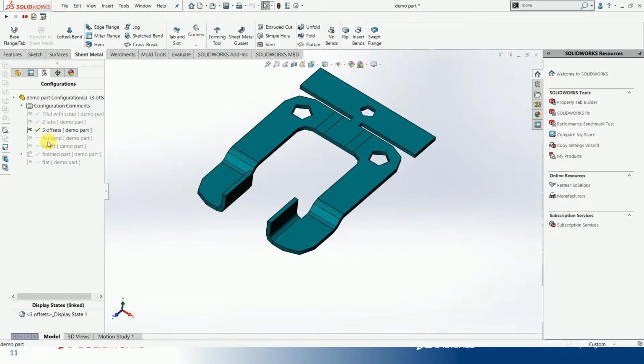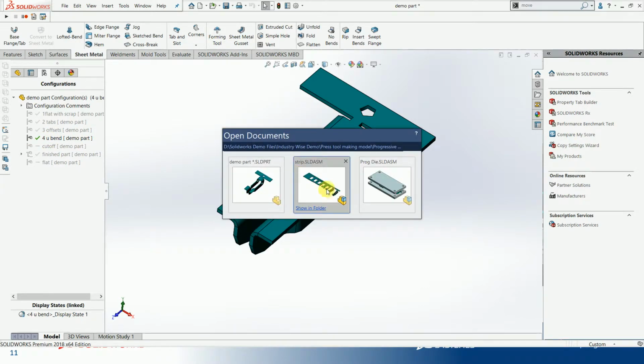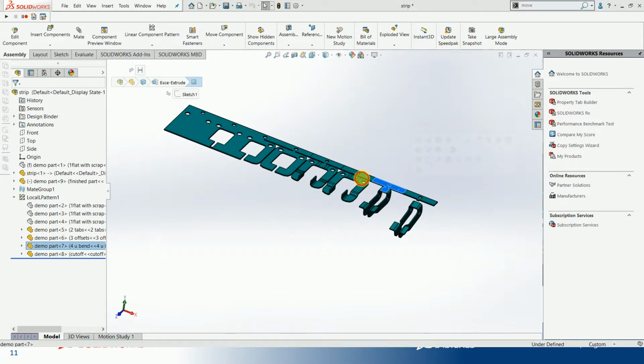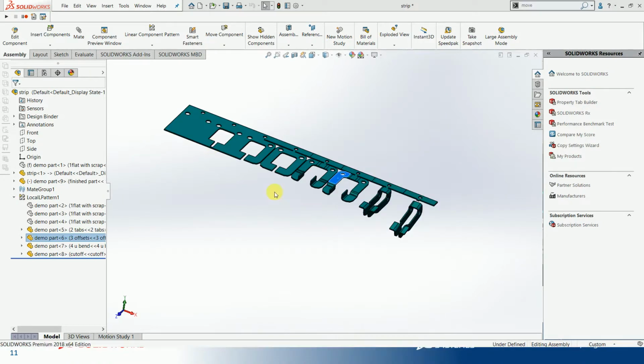Once you've done these configurations, you can bring all those different configurations into action through an assembly. In the assembly you can see the different steps sequentially by using the assembly-level configurations. In each configuration, I'm actuating the different steps that were already created at the part level. So you just assign that and create as many steps as you want.